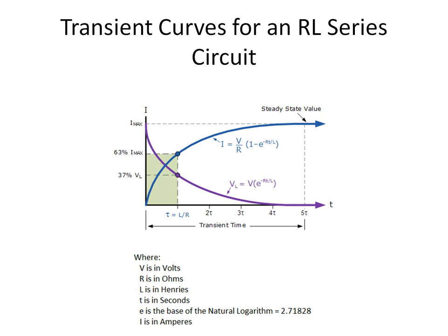Please note that for the voltage of the inductor, the longer the time from when it started charging, the less voltage it has across it. Once it reaches 5 tau, the voltage across the inductor is going to be 0 volts. Why? Because the inductor is fully charged, and when it's fully charged, it acts as a short. Since the inductor is shorted, it's going to allow the maximum current to flow. That's why at 5 tau, the current is going to be at a maximum value.